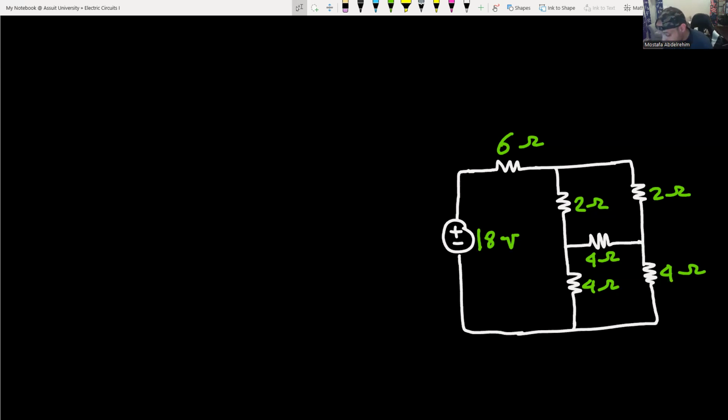So the second step is to assign a current for each mesh in the circuit. Just bear with me, I'm gonna explain what I meant by such currents. What we're gonna do is assign currents in the same rotation or same direction. So if you assume that the current is flowing counterclockwise or clockwise, make the same assumption for all other currents in the meshes.